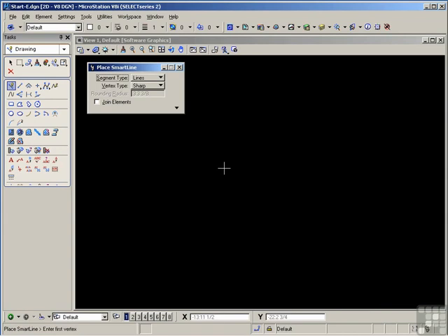It is very important that you're completely comfortable with AccuDraw's contribution to the design process. Instruction in this video and all following videos relies heavily on your ability to use AccuDraw as a normal part of the drawing process. AccuDraw is on by default when you initially start MicroStation, and you can tell whether it's on or not by looking at the line just above the status line. You should see an X and a Y with a setting box in each case. This is the AccuDraw settings box, and typically it's docked right next to the view control toggles. This is where you enter dimensional information.